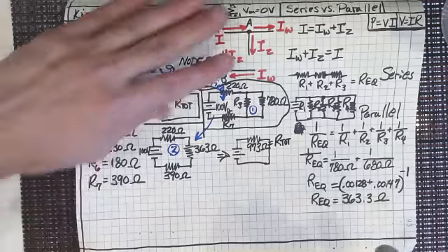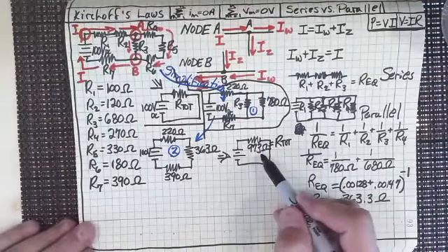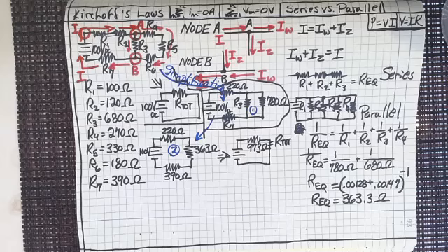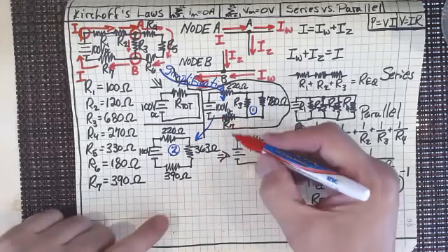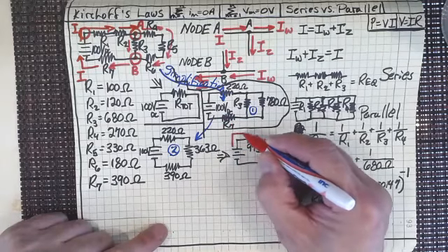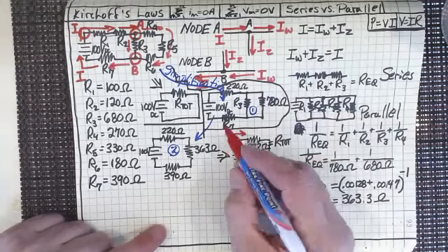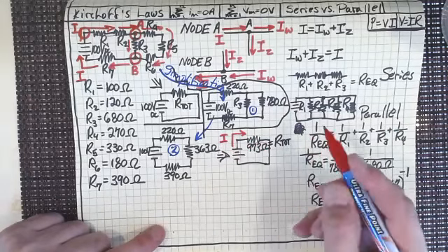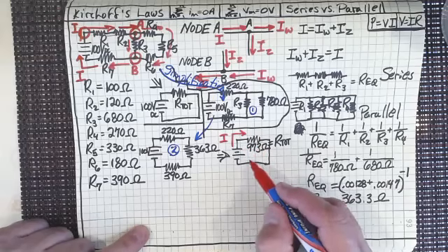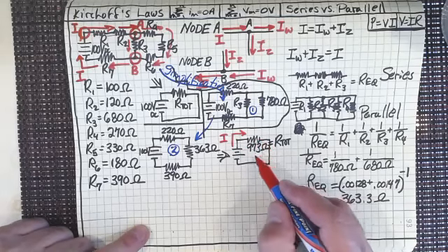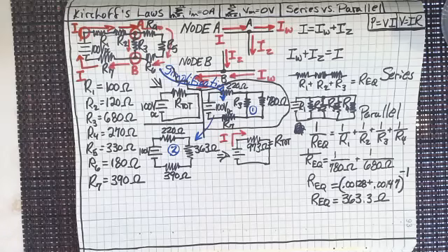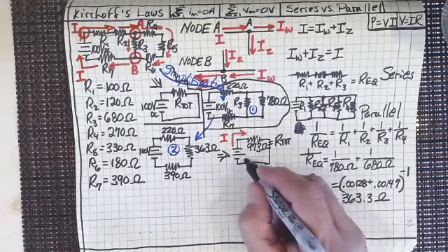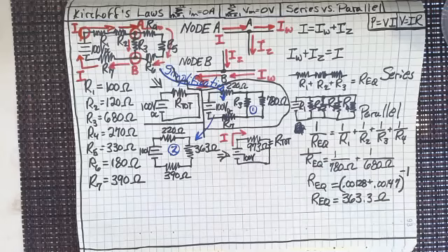And that's the first thing that you want to work with. The first thing is that we want to find out what is the current that is coming out of that power supply, right? And now we can do it because we know that really what that power supply sees when it's figuring out the current I, it has 100 volts and it sees a 973 ohm resistor, right? So that's almost 1,000 ohms, isn't it?